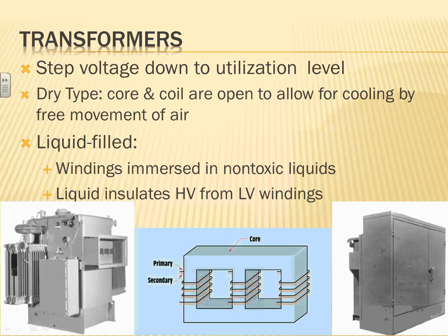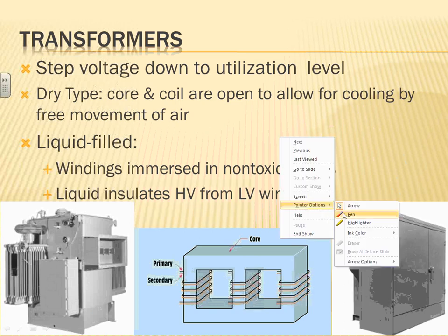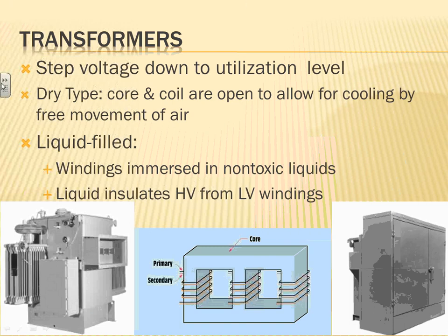A lot of us deal with transformers, and this is just a very quick review here. A lot of us deal with dry type transformers. Very few of you probably would deal with other than dry. So core and coil are open, and it's cooled by air, either natural convection of air or forced air. Sometimes they have big fans on them, and they cool them by forced air, or they just allow the natural air to cool them. That's your dry type transformer. These have a limitation on the power. I think it's 1.5 megavolt amp or something like this that you can get out of them.